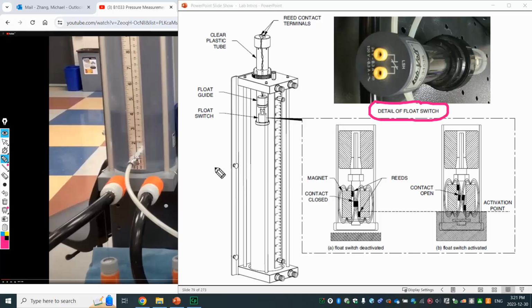The motor trainer we had there is the normally open type. You can see the connector with that. By that time I believe we used a symbol like this: two terminals, one switch, and then a float. That's the symbol we use to represent normally open. Or you can use this, but here you can see the level switch. This one is normally closed.